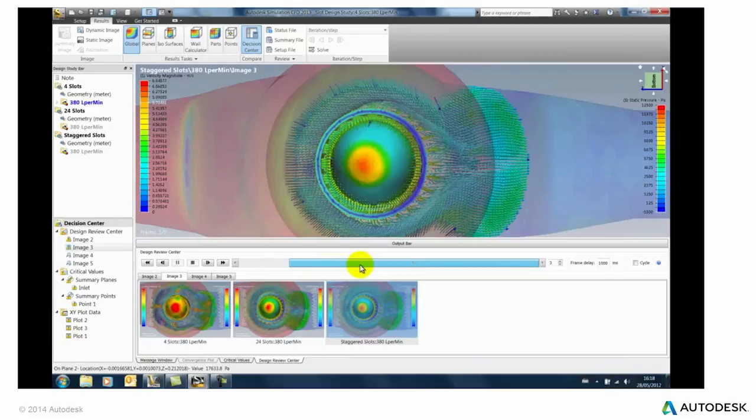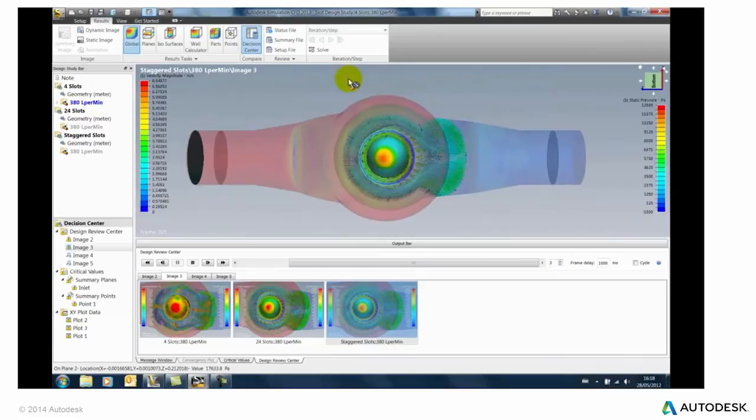Now, when we're in the CAD system, you can quickly launch from your CAD system into CFD just by selecting the tab. And then if we make a design modification, that will come through as well, and it will use the materials, the mesh, the conditions that have already been set up for your first analysis on your first design.